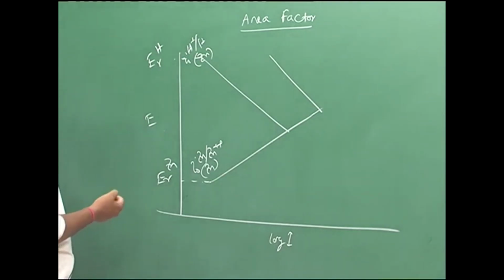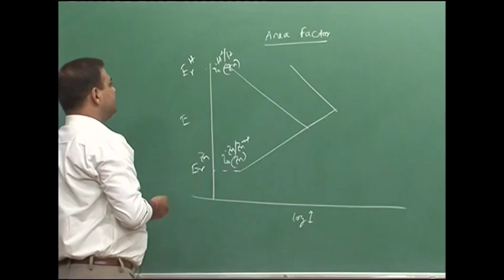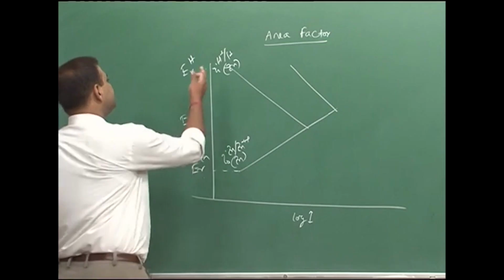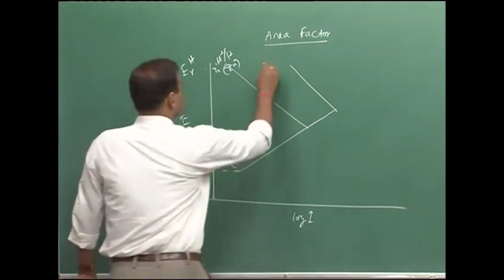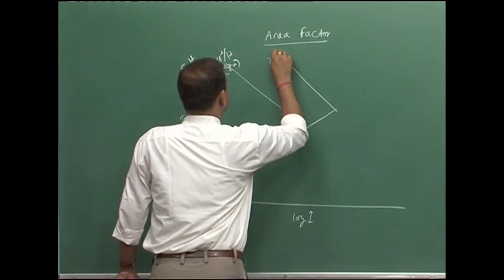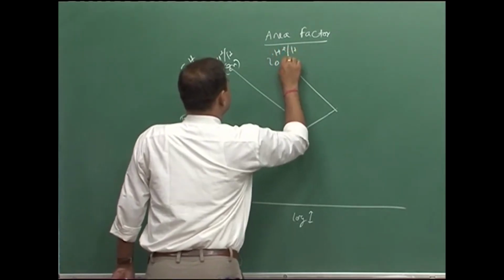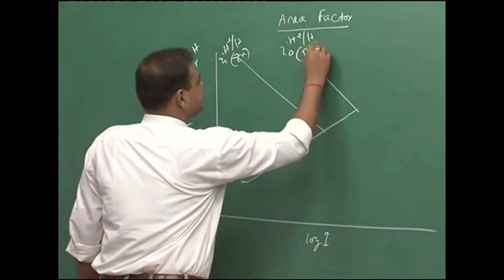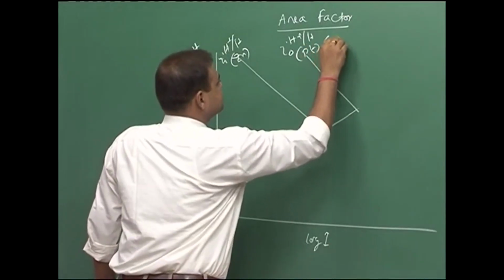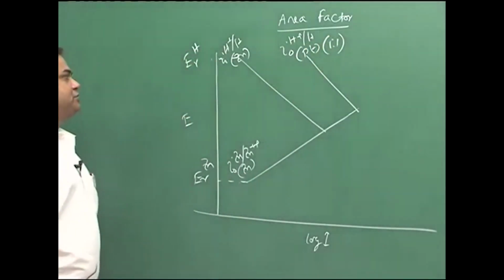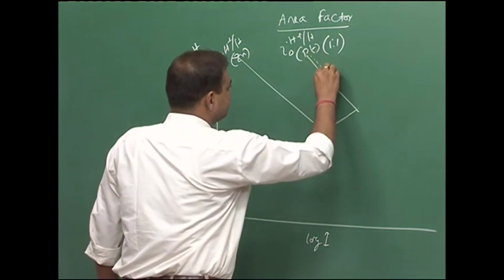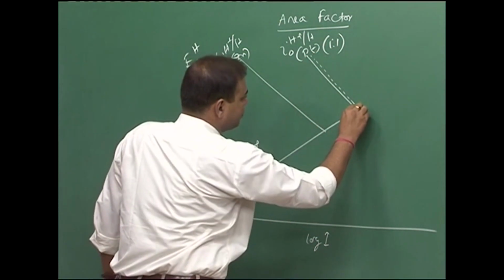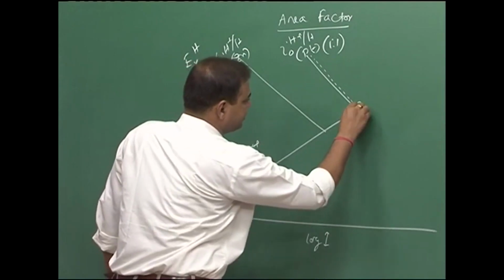And we all know that on the platinum surface the hydrogen exchange current density would be much higher than the exchange current density of hydrogen on zinc surface. So, this is the hydrogen exchange current density on platinum surface, and if it is the same area, let us say the area ratio is 1:1, then we have the corrosion current density.